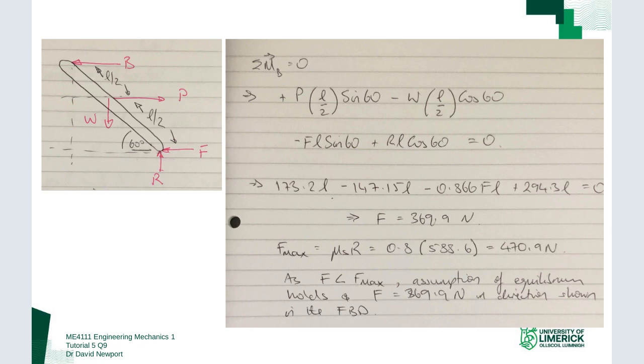And then I just work that out. And I can see that I get the friction force to hold this in place is 369.9 newtons, so 370 newtons. Now I want to check this value because this is the value I need to hold it there.